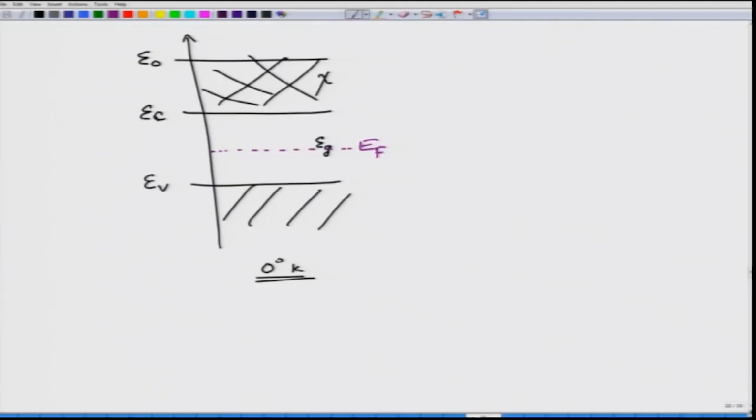This Fermi level tells you, and this is a property of the material, of course, for different materials they have different Fermi levels, and for this material which we are considering, what this Fermi level signifies is that if at all this Fermi level were to be available for the electrons to occupy, that is a very important point here. If the Fermi level were to be available for the electrons to occupy, then the probability of the electron being found at the Fermi level will be about half.